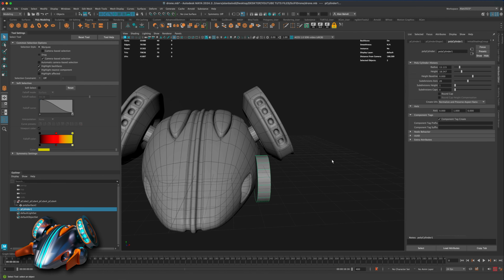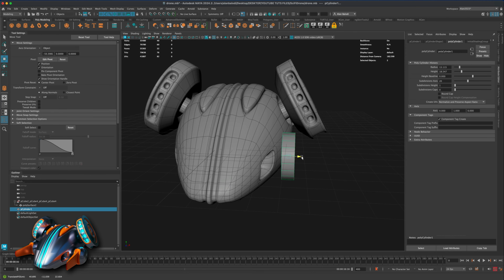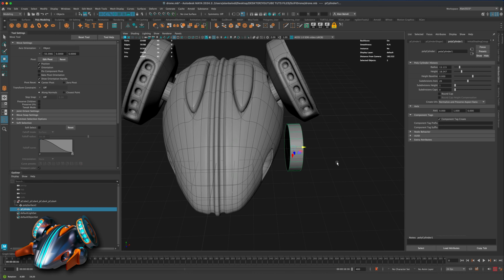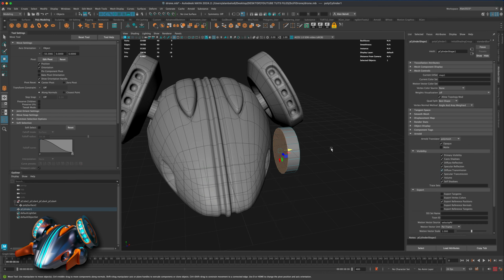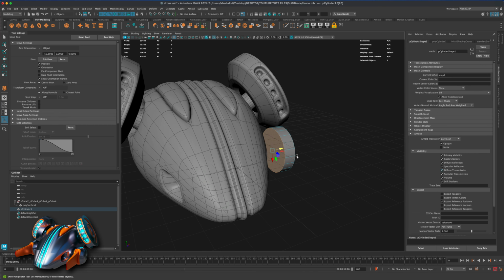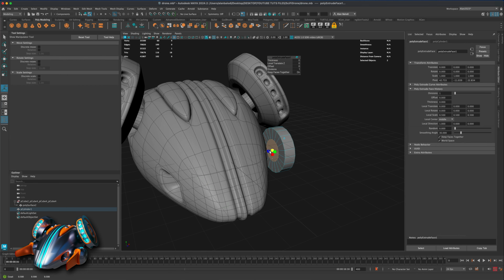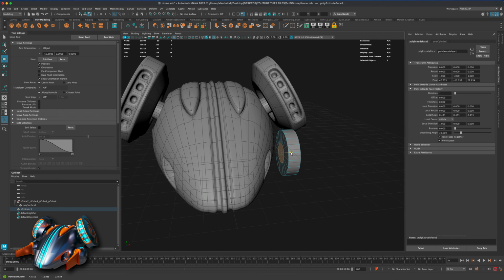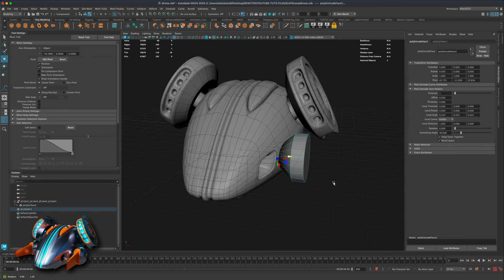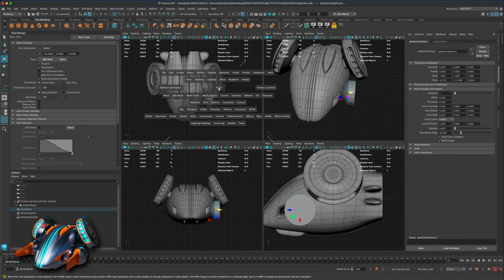Let's go into perspective view. I'm gonna press W and make sure it's not touching the side here. All right, I'm gonna grab this face here, press Control E and scale it in. Press W and just move this in this way. All right, and then I'm gonna go to the top view.